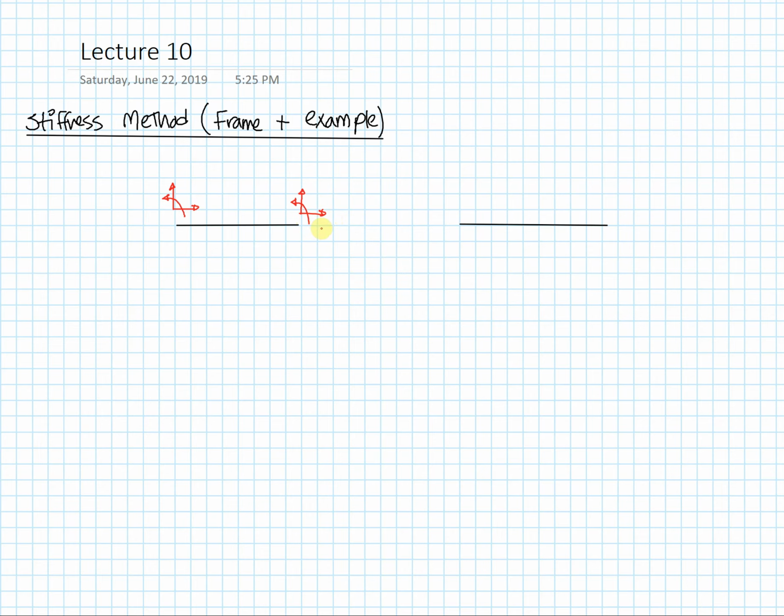We're going to assume they are small, and so we end up with flexural and shear components of the degrees of freedom. So you can imagine we have shear components Fy1 for any element, and we also have M1. We're also going to have an Fy2 here, and then M2.